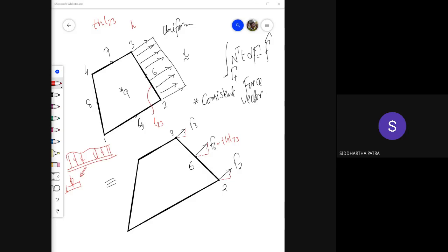When you move on to strength of materials, you obviously have thought about deformation of the geometry, and the thing is, yes, I agree that the net resultant force actually acts over there. But this resultant only takes care of the net force in the system and the net moment in the system. If the system actually deforms, it doesn't take care of the deformation.